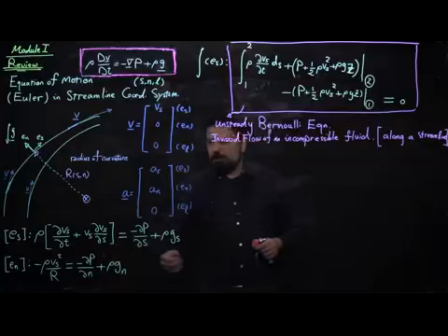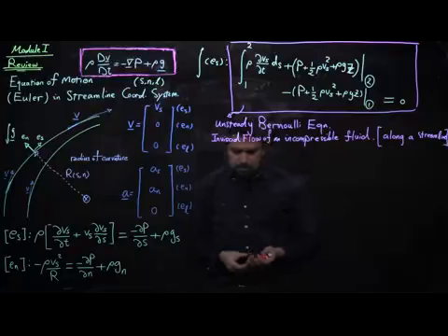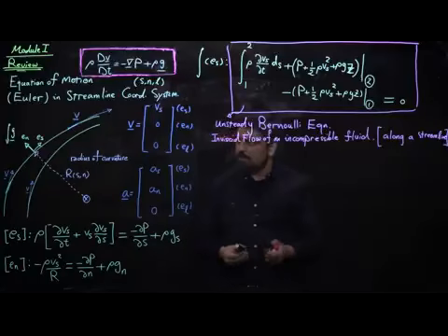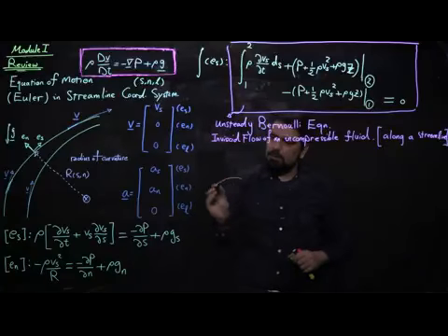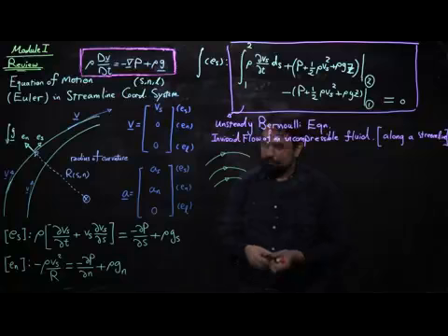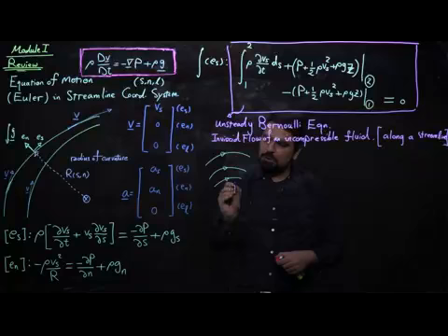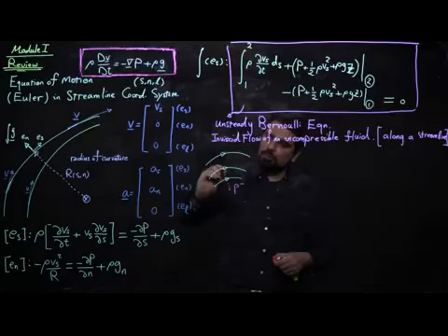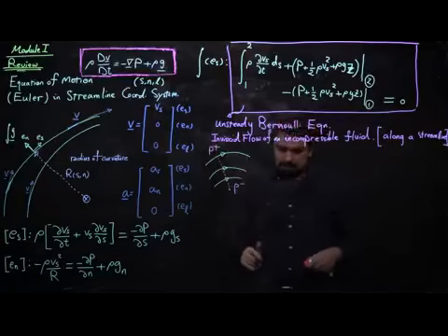The normal component of the Euler equation gave us some interesting physical intuition too. We understood that if we have certain streamlines that are curved, for example, if I look at the typical streamlines of flow in a hurricane or ideal vortex, as we discussed extensively in the class, we notice one thing that is very interesting. At the center of rotation, pressure takes its minimum value, and as I go normal to these streamlines, pressure increases to larger and larger values. So you have a gradient of pressure field that comes due to the centripetal acceleration.